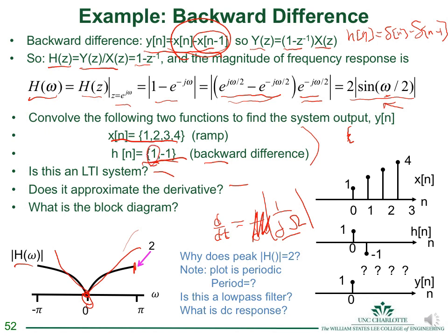For the second step, I have a weight of minus 1 that would multiply this shifted by 1. And so I have minus 1, minus 2, minus 3, and I got to take this one further, minus 4, so let's put a 0 here. And then I add all those together as the total response. And so if I add those together, I would have a 1, 1, 1, 1, minus 4. And so if I draw that down here, 1, 1, 1, minus 4.